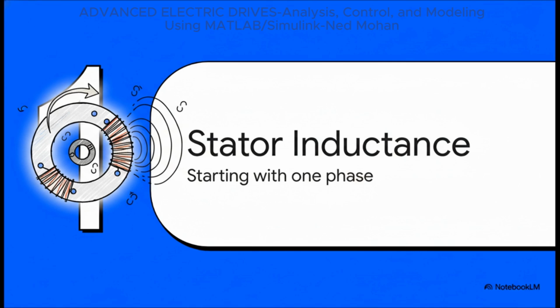Every complex model really starts with a simple assumption. For us, that means we're going to look at the stator by powering up just one phase, phase A. And we'll just imagine the rotor is there, but let's say it's electrically switched off, or open-circuited. This is a great trick because it lets us focus purely on the stator's own magnetic properties first.